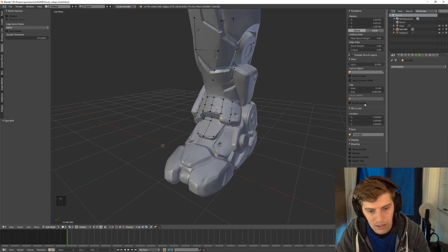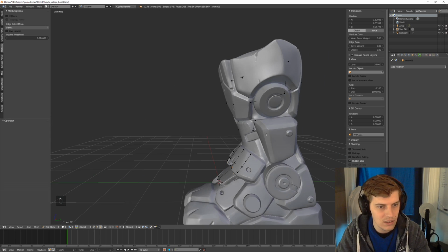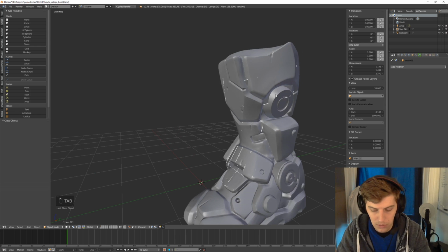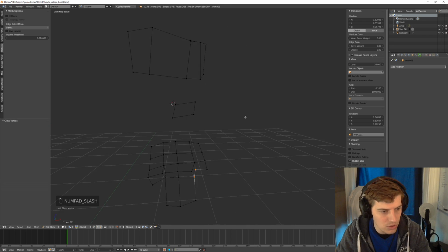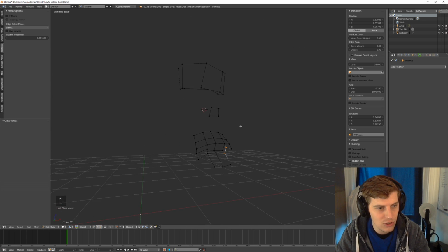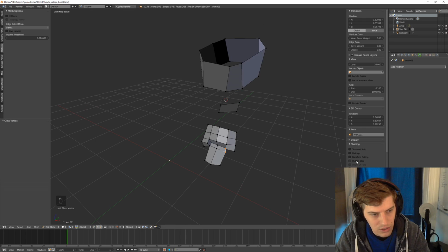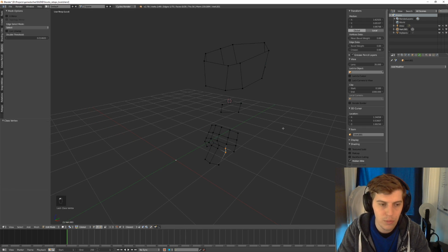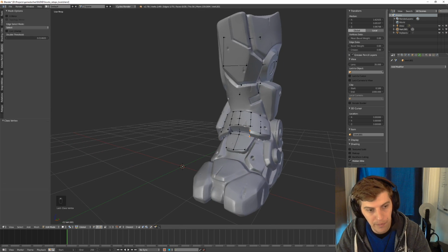One of them is you can start off by, under the panel here on the right, you can select hidden wire. And what hidden wire does is it basically, let me see if I can illustrate this. If I go to object mode, and well, I don't have to go to object mode, I can stay in that mode. I'll isolate the mesh, and now I'm just seeing this mesh, my low poly mesh, and you'll see that it's basically just showing kind of like a wireframe essentially. And if I turn this off, it shows me the geometry.